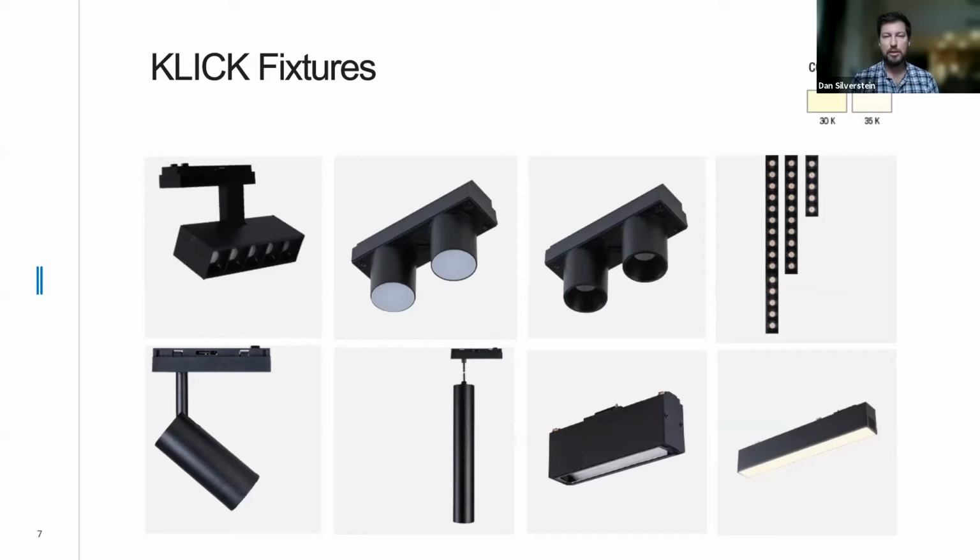The next fixture to the top right is the next two fixtures that we call the goggles. The modular goggles with the lens in front of it give a nice diffuse light if we're trying to do countertop lighting and illuminate spaces 4 or 5 feet away. The one to the right of it is spot goggles that are 10 degrees and really throw a punch. So those are great tools if you want to do illumination greater than 5 feet, 5 to 15, even 20 feet away. That'll throw a really nice tight beam.